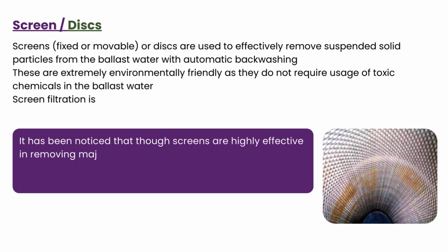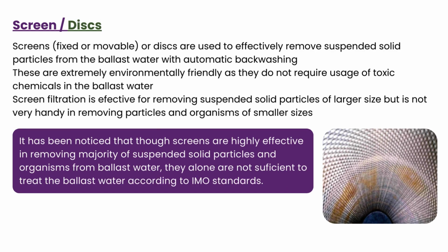Have a look at this. We have the filtration, the screen, fixed or movable or disc, used to effectively remove suspended solid particles from the ballast water with automatic backwashing. These are extremely environmentally friendly as they do not require the usage of toxic chemicals in the ballast water.